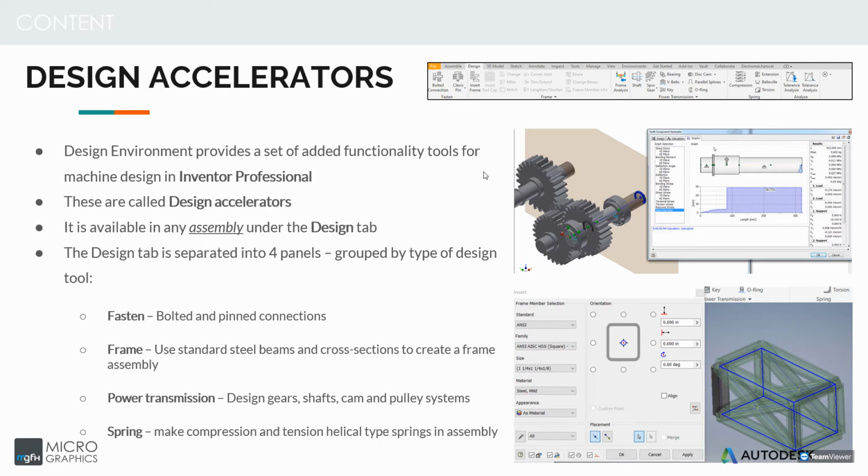These tools are called design accelerators. Just some terminology there to know what Autodesk calls it in Inventor. It is available in the assembly under the design tab. So you're not going to find it in the part environment, only in the assembly environment.